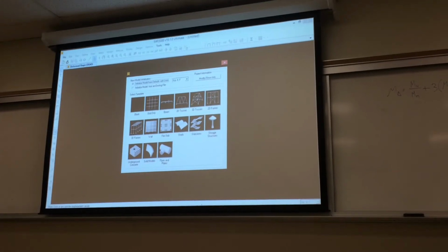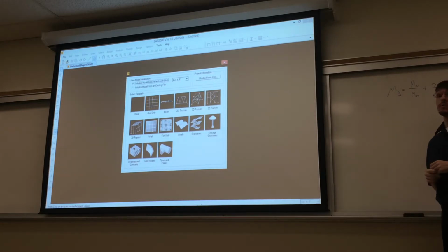One of the big things you want to keep in mind when you're doing this sort of computer modeling is this is an analysis set of software. This is not a CAD piece of software. So you don't want to think in those terms where you're drawing everything in CAD and then it magically knows how to take your CAD drawings and do all sorts of appropriate analysis on them. Finite element software is much, much different than that. It basically solves all your problems by looking at displacements. So you have what are called nodes, these individual points in space, and you connect these nodes with members.